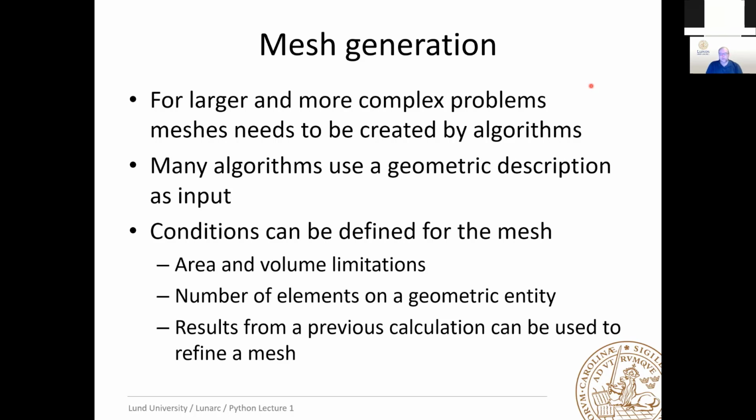In many of these algorithms, you can also take the results from a previous calculation as input to refine the mesh. For example, if you have high stress concentrations, you can use that as an input to refine the mesh and add more elements at those points.